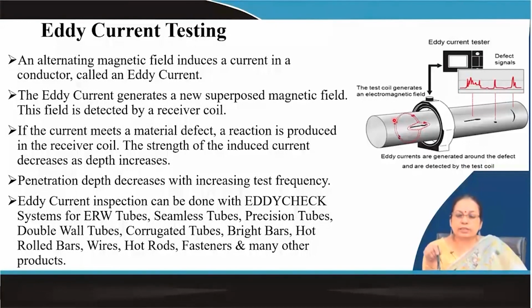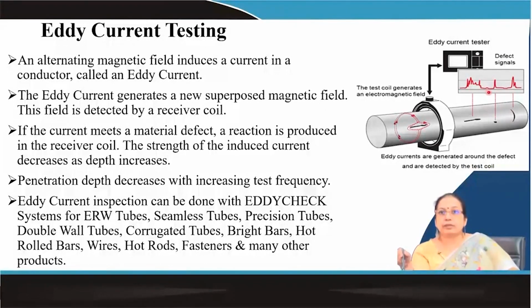From the location and the signal itself, you determine the defects and their locations. This is again a very easy way. For example, these are typical recorded electrical currents, and where there are flaws, here and here, you see a change in the signal, so you can determine the defects present on the surface.